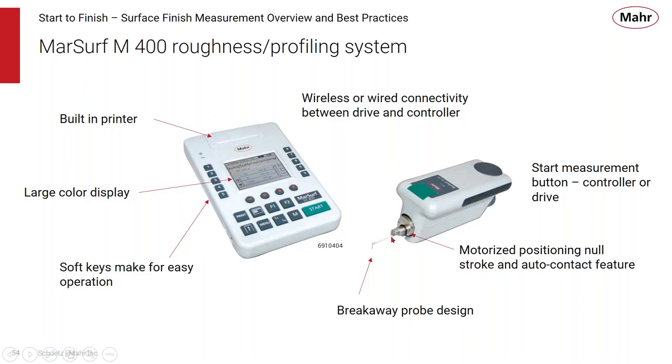We use a unique breakaway probe design. Now you can imagine with a profiling system that the stylus has to be a pretty fine and delicate piece of equipment. But rather than having a stylus that is fixed to the probe, we use magnets to hold the stylus in place. So if it's subjected to a quick hit or something like that, the probe will just break away based on the magnets, and then you can put it back into place.